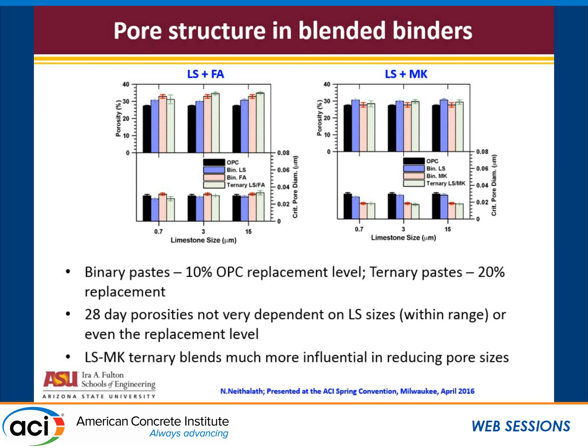It's been there. But while we reduce the porosity, you automatically infer that porosity reduction will result in a concomitant reduction of sizes in pores also. That was our assumption. It need not happen all the time. You can have pore volume reduction without really pore size reduction of large magnitude. So here what I want to show you is that it is the pore sizes that are important in transport. So measuring a total overall porosity might not give you the actual picture when you're looking at transport, not just for limestone concretes, but for pretty much any concretes.